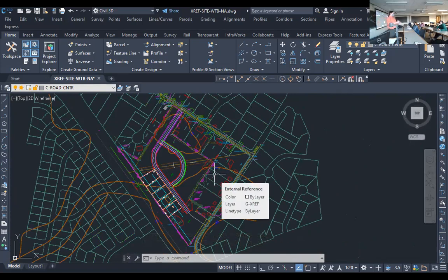The easiest thing is to have one continuous polyline for the whole thing. And you want to make sure your curve is tangent at the two ends. The easiest way to do that is with a fillet. You can do curve, tangent, tangent, like I showed before.